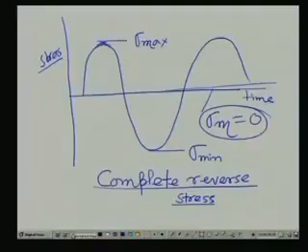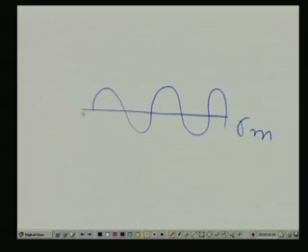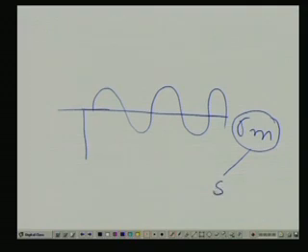Before coming down to the other types of stresses, let us be clear on one thing. The basic concept is that if you have a mean stress line, then the stress amplitude is something over that. If we consider the mean stress, then we consider the design to be static, because mean stress somewhat resembles a static load.